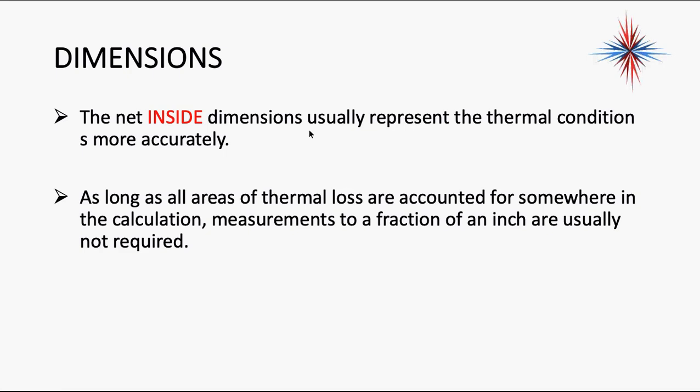Okay, remember a couple of you asked me if you need the outside dimensions or the inside dimensions. Again, this is why I said inside is fine. Inside dimensions usually represent the best thermal conditions. It's more accurate because it's your inside area, inside volume we're talking about. We account for all areas of thermal loss when we start talking about walls. Don't go to a fraction of an inch. We want to go to our closest inch. Don't do decimals if you can avoid it.